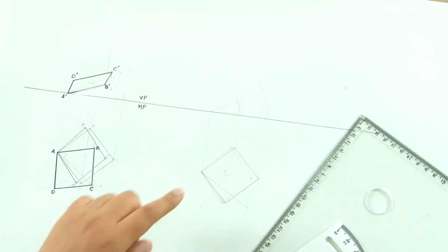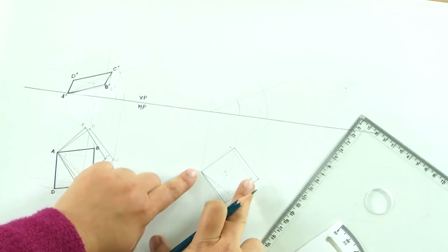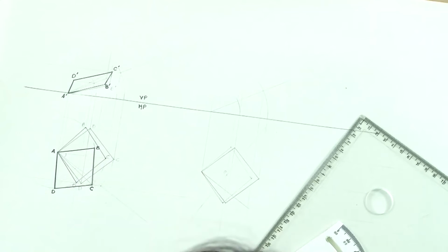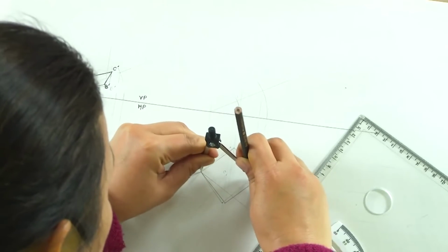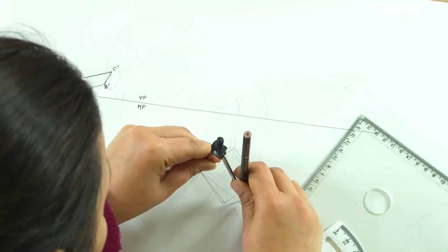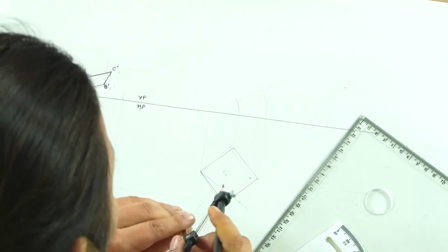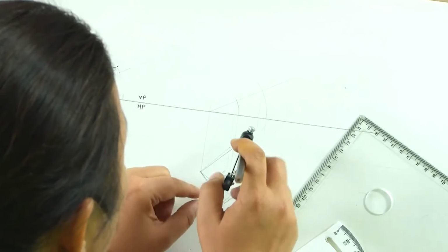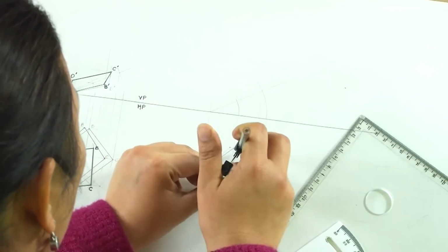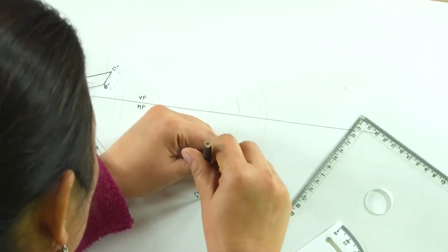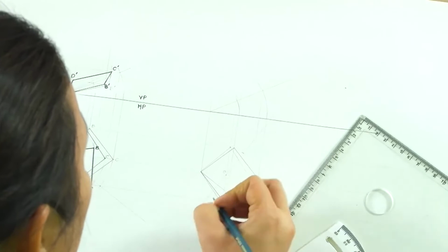Now, we know that this point B and this point D are going to lie on this line, and this point C is going to come onto this line. We will only take the distances and then move them. So, this distance AC is now here onto this diagonal, which is the new C, and perpendicular to it, this distance O to B will now be marked here, which is going to be the same distance as O to D. So, the final shape of this square is this.